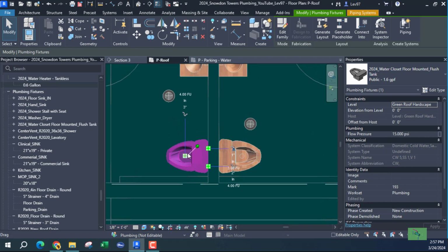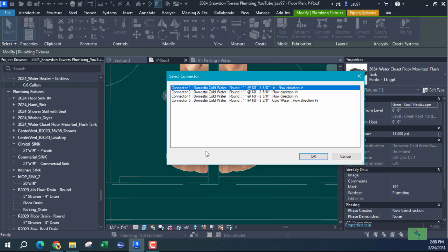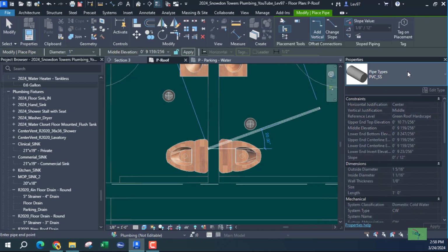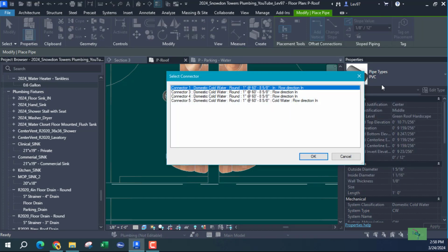Well, I'm gonna go here first. Let's go. I'm thinking maybe I should go, well, let's get the pipe over first. Okay, so I'm gonna say okay to this, and I need to change the pipe type to PVC. I'll probably end up changing that to PVC. Do I change it to hot water, cold water, different types? It depends. It depends on your office standards.